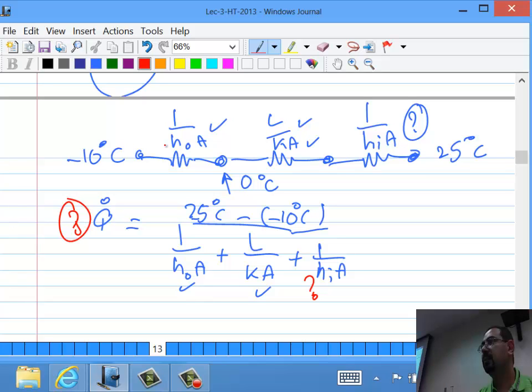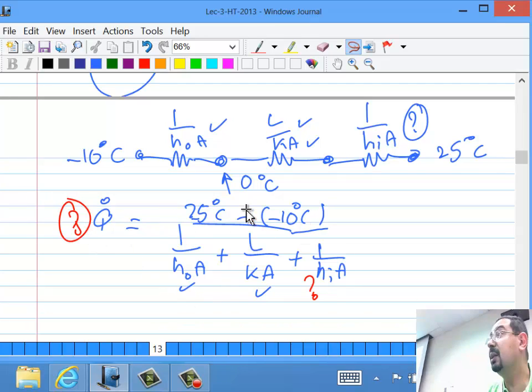Or he can give you the Q and the delta T and say, well, how thick is the insulation that will do this? So he can then ask you about the L. So there are no real surprises here. There is this one equation. You need to have everything known except for only one variable, and that is what you are trying to calculate. It's not okay to have two unknowns. That doesn't help.